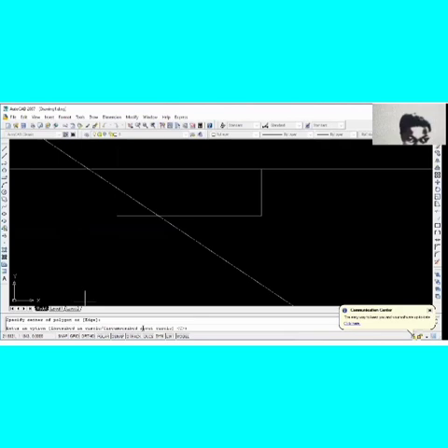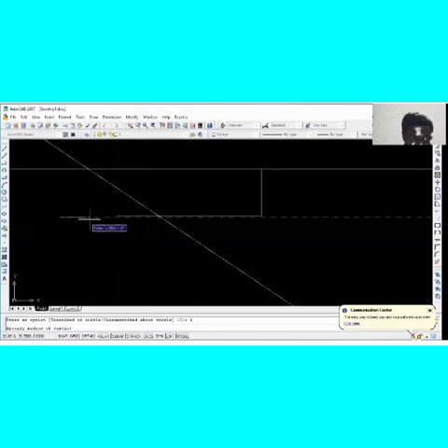And then it now says I or C. So you can decide to type I or C. Okay, let me choose I. I means inscribed, while C means circumscribed. So type I, and press enter. And then you can choose any position depending on the radius of the circle. You can type a radius, or you can decide to just click it.